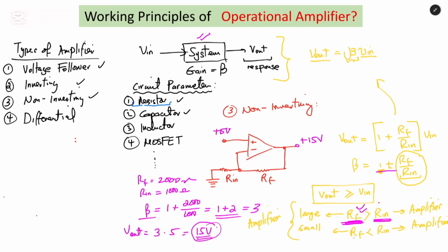So what will happen now if we look at this example? We decrease the feedback resistor and increase the input resistance in this circuit. So what I mean by the input resistance is the input resistance to the inverting amplifier. So it will mostly act as a reference. So Rin is the input resistance to the inverting, which becomes the reference of the non-inverting input.